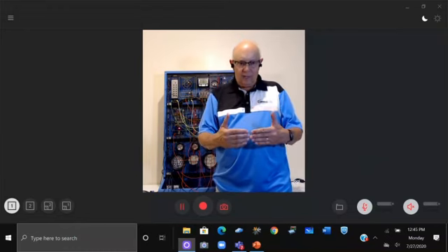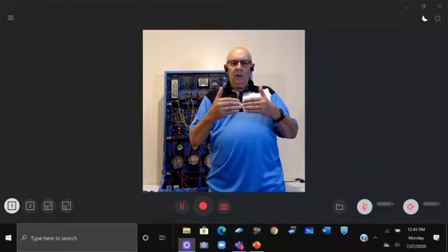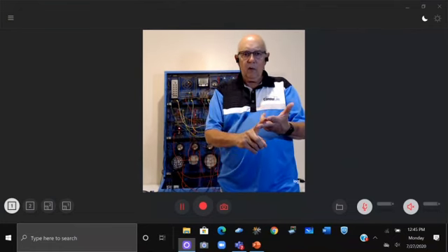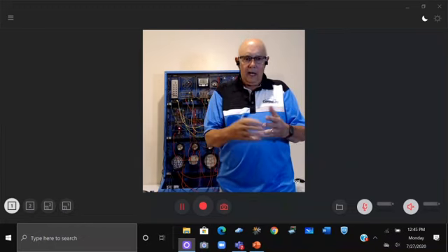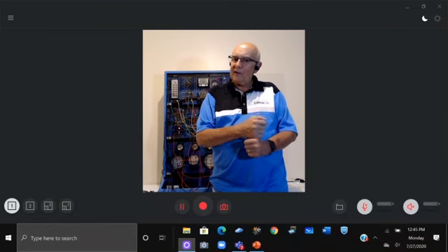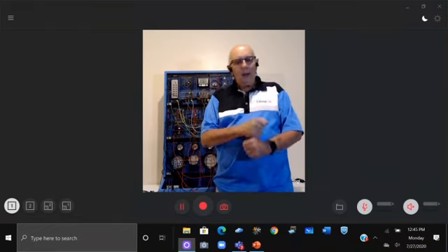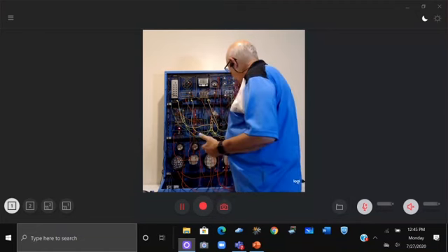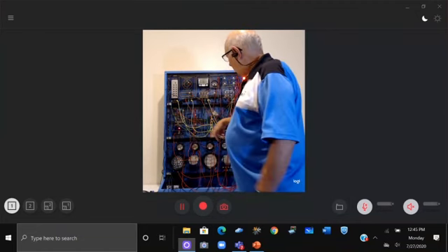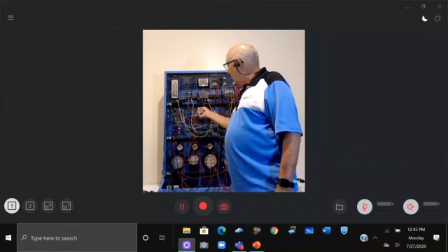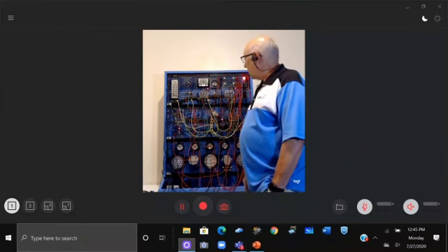Conceptually, what we're trying to get across to students is the first thing we need is power. The next thing we need is ground. After that, we need CAN high and CAN low. And then if you go all the way back to the beginning, remember one of the things I talked about? A wake-up signal. Something has to wake the vehicle up. We have a wake-up signal built in. So I'm going to flip the wake-up signal up, and you're going to notice a couple of things.